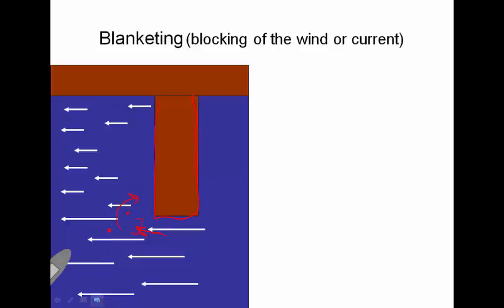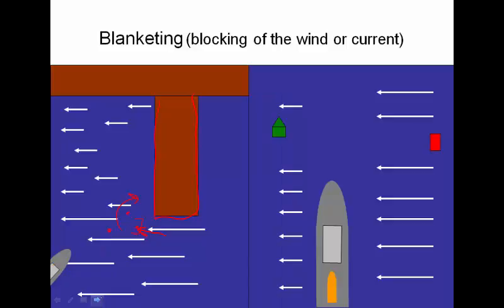Another example would be a vessel moving ahead in a channel. We're going to say this is our wind. So we have a heavy wind that's pushing in the direction of the arrows listed here. This is a floating buoy, and this is a floating buoy. What's happening at the bottom? Well, this buoy is actually attached by a bunch of chain to a sinker, just as my starboard marker is as well. Now, if I have a lot of wind, these guys are not going to be directly over their sinker as I've drawn here, but they're going to be closer to this. The wind's pushing them and the chain's holding them in place.